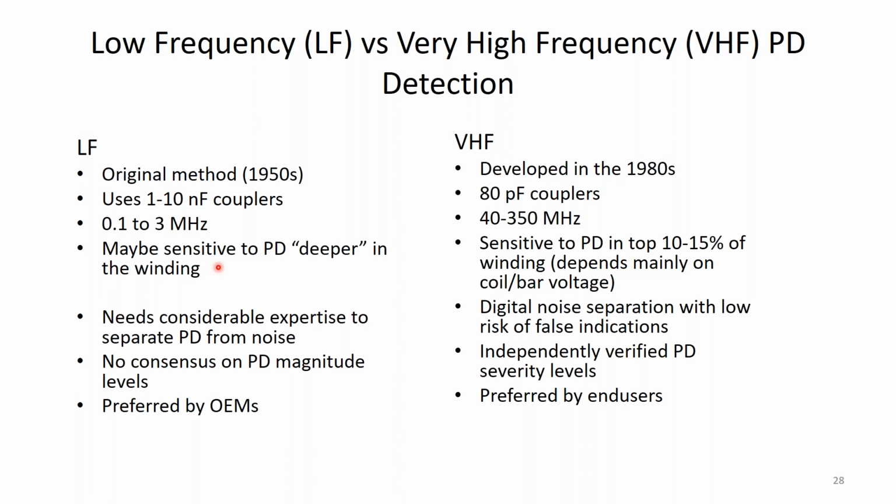And as I said before, there is no consensus on what's high or low PD. When we look at who buys the systems, the low frequency technology tends to be bought by the OEMs and the service shops who provide testing services. In the VHF, it's just different, okay? It is easier to separate the PD from noise. That's recognized in all the standards, and most people will acknowledge that.